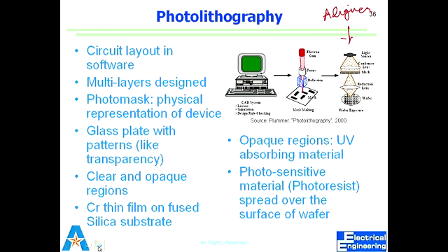We put this into what we call a lithography system. So this is my mask, and I shine the light. Light travels through some optics, resulting in formation of this design in that photoresist material. Essentially, it doesn't make that design. What it does is it changes the property of that photoresist material in those places wherever that light reaches. Right? We use photolithography, using ultraviolet, 365 nanometer, 405 nanometer.